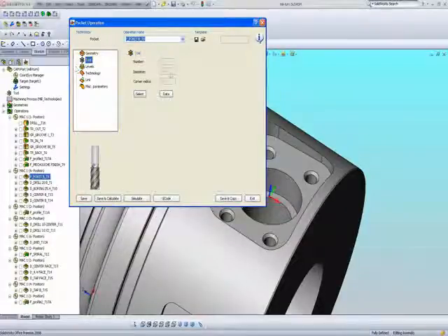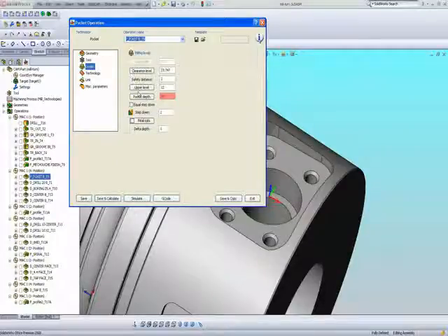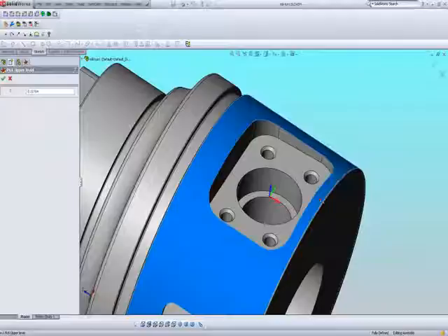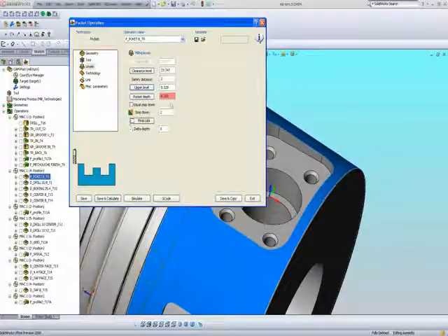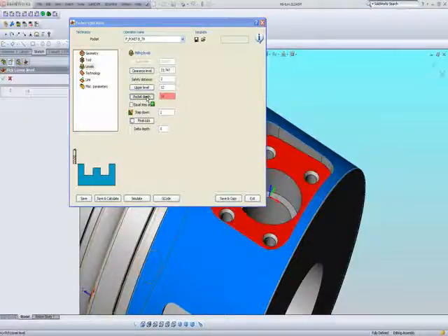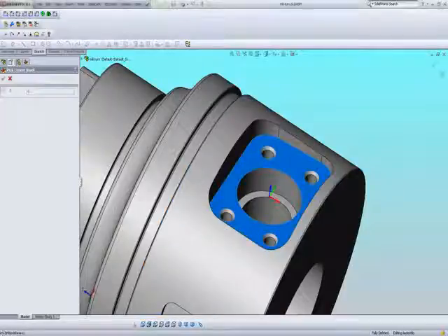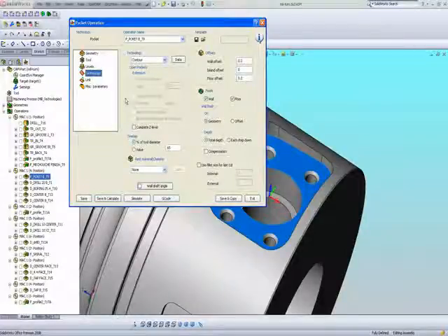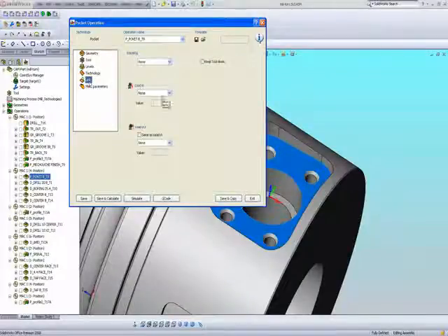The tool that I will be using will be a regular end mill, 16 millimeter end mill. My levels, my upper level, is actually taken over here, but I've made it go up a little higher than that. I've written 12 millimeters. And my pocket depth is up until the floor itself. In my technology area, I'll be using a simple contour option of pocket machining, where my link, I can have a lead in, lead out any way I want to have it.